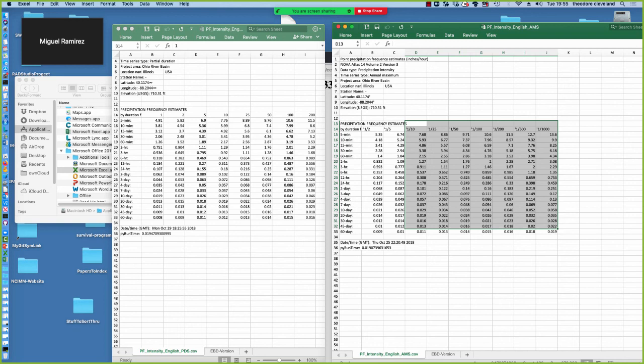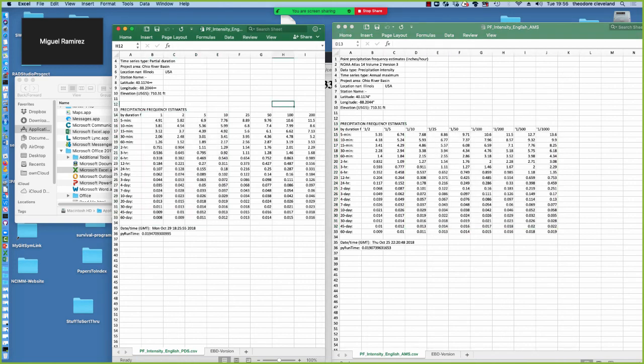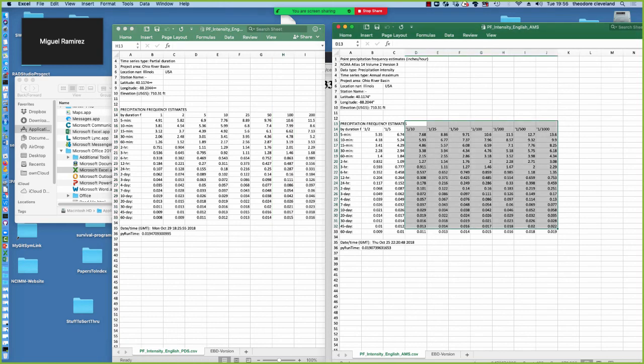So like the city of Lubbock, when we're doing stuff like this, they say to use like the 100-year storm. So the annual max series would probably be the better one, right? Yeah, use whatever the design document says, but for the 100-year storm, there is a partial duration representation of a 100-year storm and an annual maximum representation of a 100-year storm. Fortunately, at the 100-year and the higher magnitude things, the difference between the two approaches is almost indistinguishable.